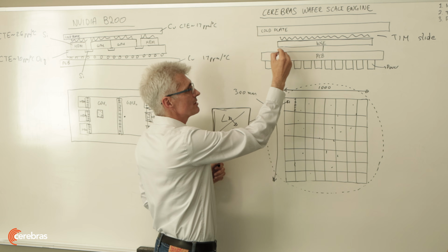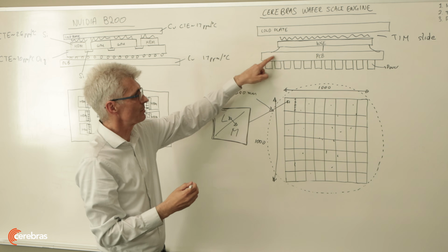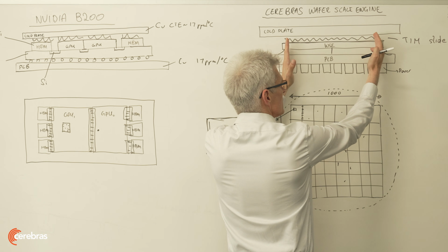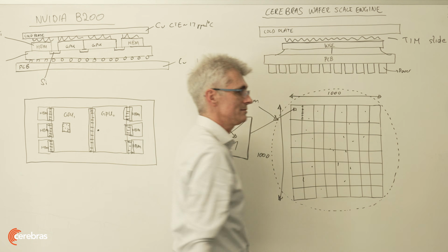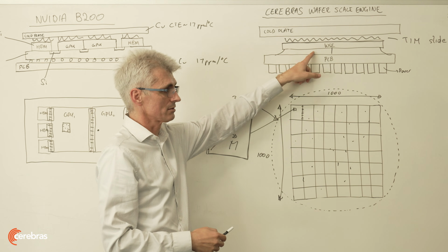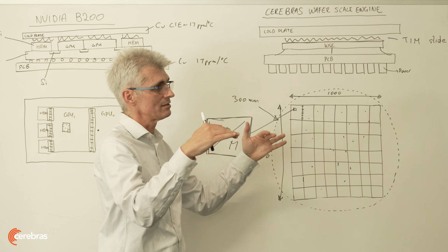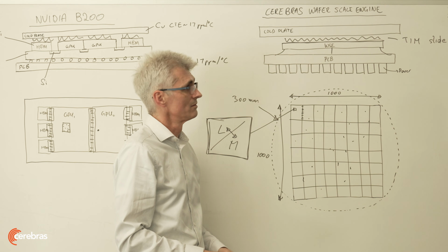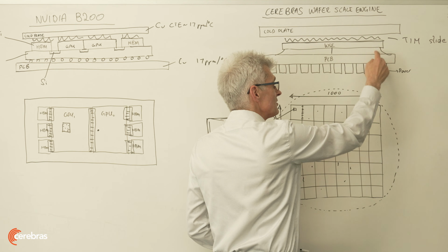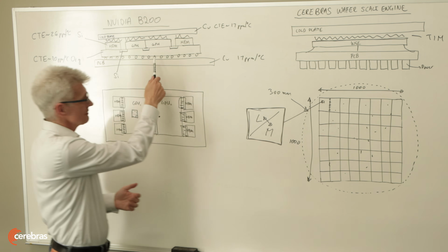But then on the edges, you might have a different thermal expansion of the PCB that causes these connections that are initially vertical to start to bend with temperature. We invented a connector that can actually cope with that deflection, that CTE expansion. You invented a flexible connector, one that... A connector that can actually allow the two pieces to expand at different rates while maintaining connectivity. In this case, they can't.